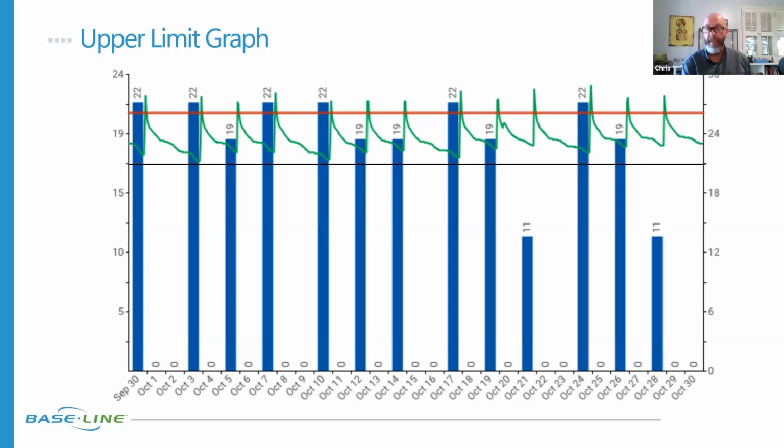So you need to be cognizant of that and give it the opportunity to apply that first application to break the surface tension of that soil, apply a second to help to force that first application of water into the soil profile deeper, and the third one to really accelerate that capillary action through the soil profile. So we're getting nerdy today